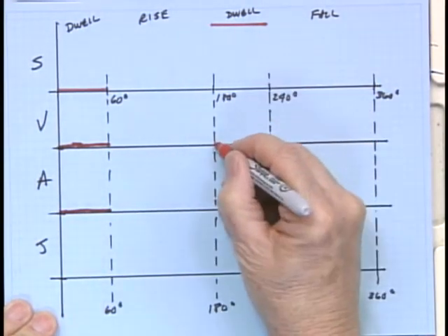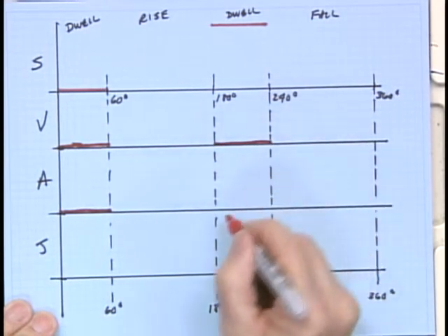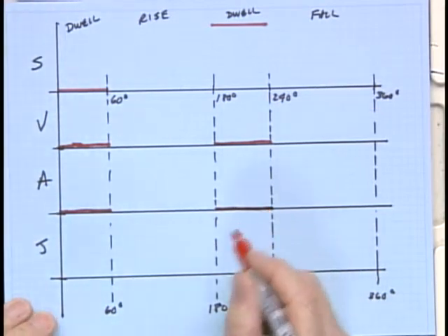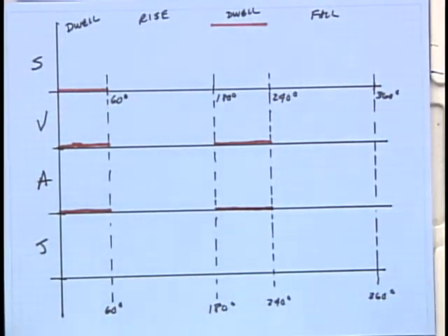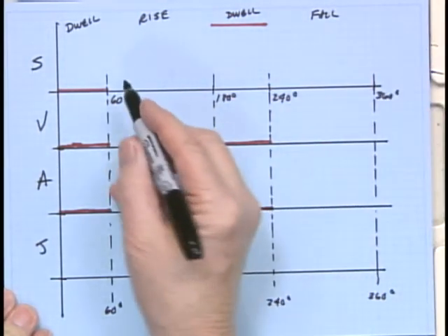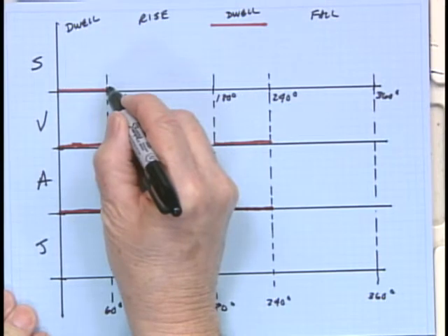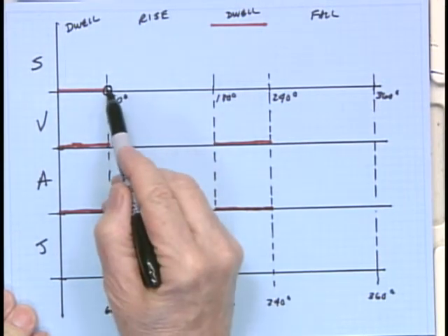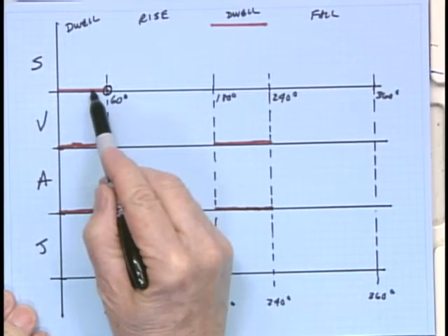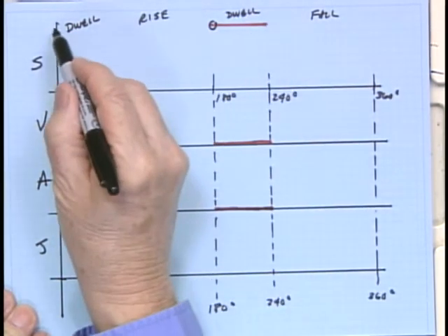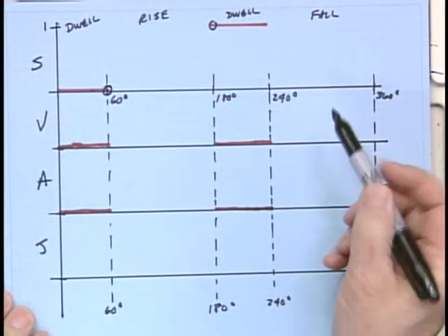So during those events, which bracket the rise here, in our case, I have 0 values. Well, in order to maintain continuity, i.e. obey the fundamental law, I have to have a value of my displacement rise of 0 at that point to match this, and I have to have a rise of, we called it 1 for this example here.